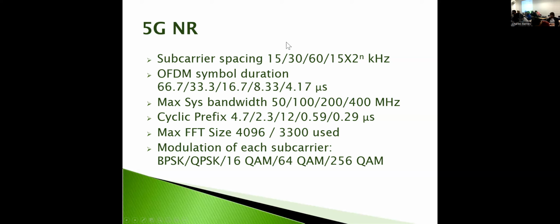But when we take these subcarriers and get a bunch of them, we do this IFFT, then with this standardized sampling time, our OFDM symbol durations start at 66.7 microseconds long, right?